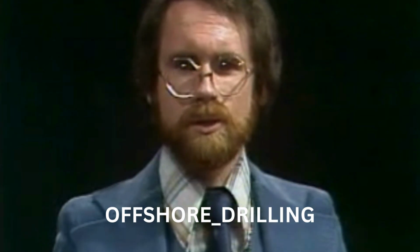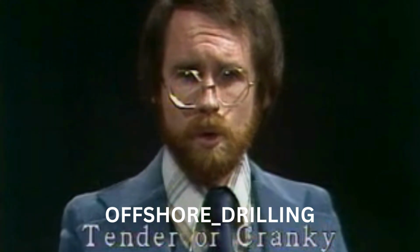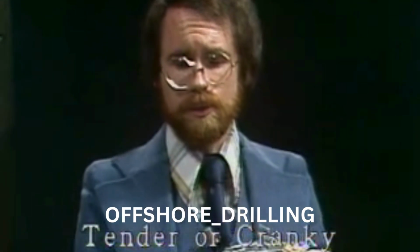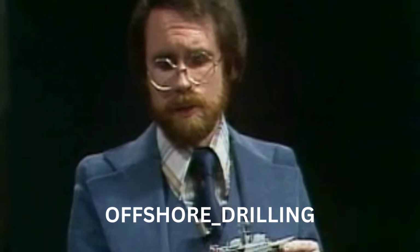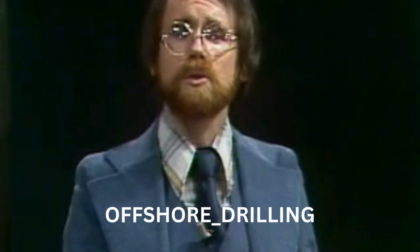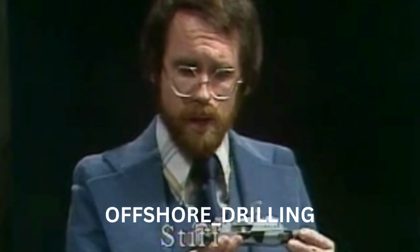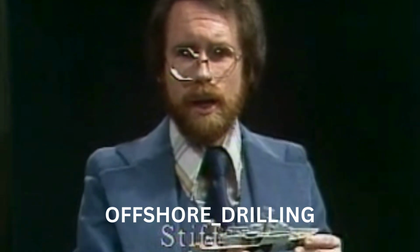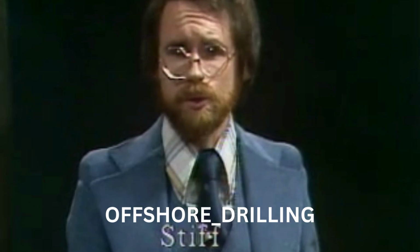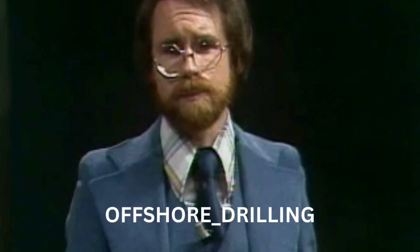A vessel that is top-heavy is said to be tender or cranky. It has a slow roll and a weak tendency to return to its original upright position. Here, the stability is considered to be poor. A vessel with most of its weight located towards the bottom of the vessel is said to be stiff. Its roll is quick, and it has a pronounced tendency to return to the erect position without much roll. This vessel is said to have excessive stability.